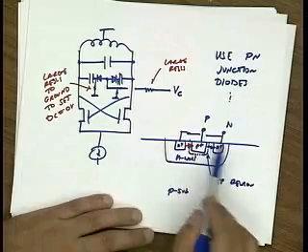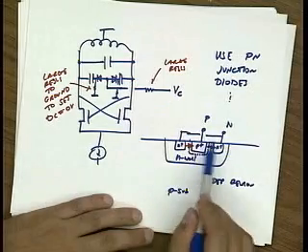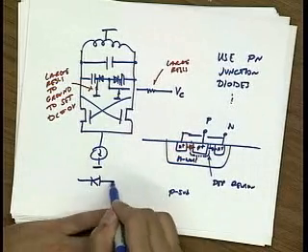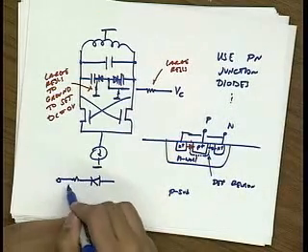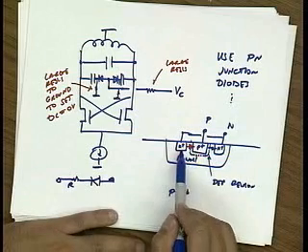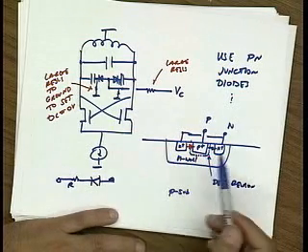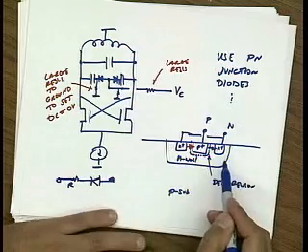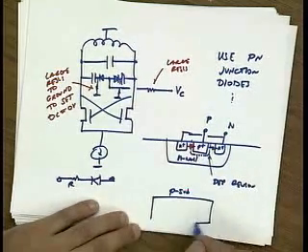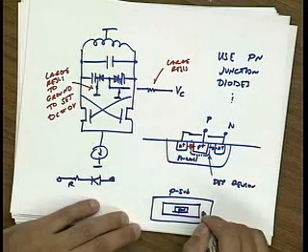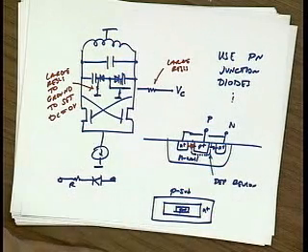Unfortunately this diode has some series resistance. It has a finite value of Q. So the equivalent circuit looks like this. That's why I've put 2 N plus contacts around it to reduce this resistance. In fact, what would be better is if I put a ring around it. From a top view, this would be the P plus, this would be the N plus, to try to minimize that resistance.